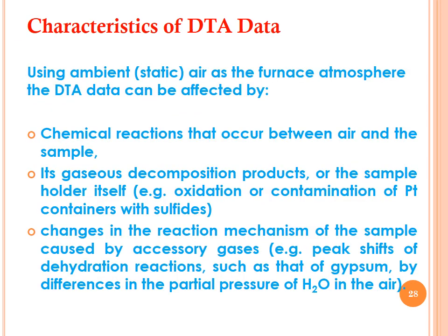Using ambient static air as the furnace atmosphere, the DTA data can be affected by chemical reactions that occur between air and the sample. It may be a reaction between the sample and air, maybe oxidation occurring as a result of the reaction of air with the sample.